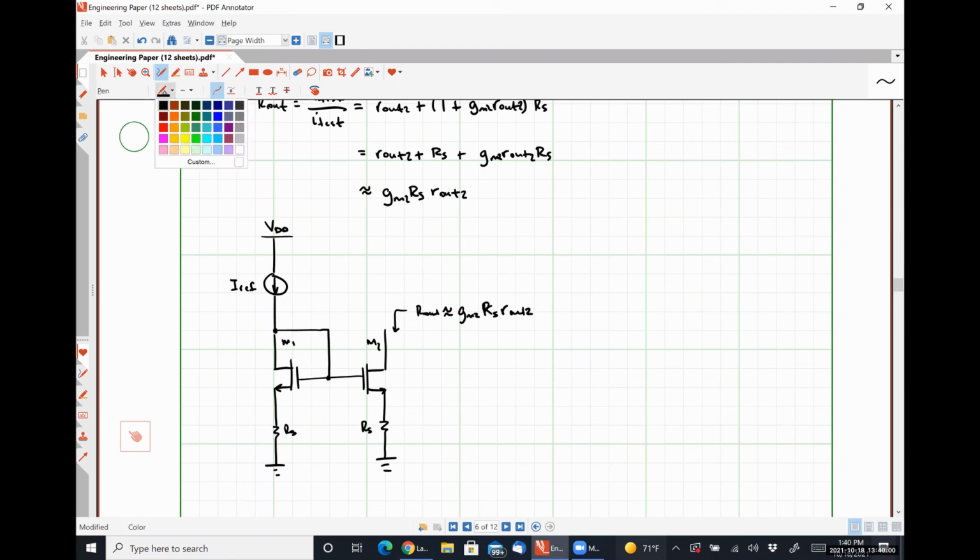So the problem that we are going to have, I'll draw these in red, right? I have to include this resistor connected to the source of transistor M1 as well, right? This thing has to be perfectly matched on the left-hand side to the right-hand side so that the current is mirrored correctly. Well, that resistor will experience a voltage drop across it, right? That will be exactly equal to IREF multiplied by RS.